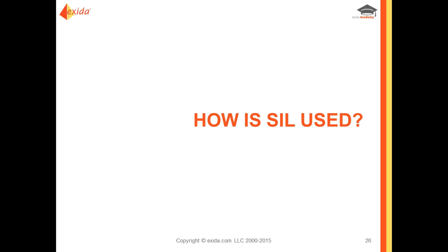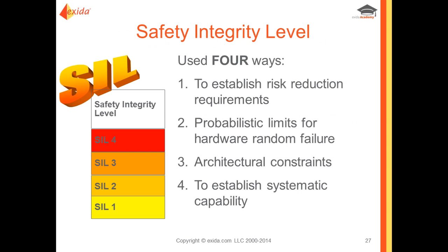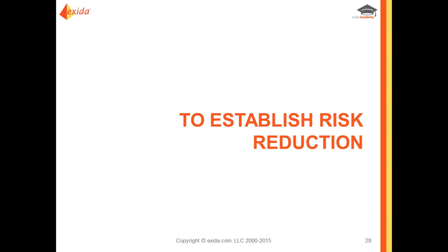So finally, we're going to look at the PFD average calculation and how that is found. The PFD average is based on the dangerous failure rate, system diagnostics, proof test coverage, test intervals, and a few other things. Typically, a final element assembly will have a PFD average that only meets SIL 1. However, there are things that can be done with diagnostics and the proof test that would improve the PFD average to SIL 2. And we'll show examples of this and talk about how you can do this later on.